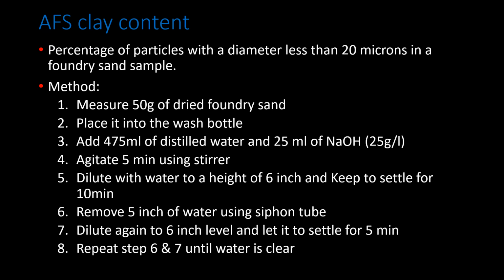AFS clay content. First measure 50 grams of dried foundry sand. Then place it into the wash bottle. Add 475 milliliters of distilled water and 25 milliliters of NaOH. Then agitate for 5 minutes using a mechanical stirrer. Dilute it with water to a height of 6 inch and keep it to settle for 10 minutes.